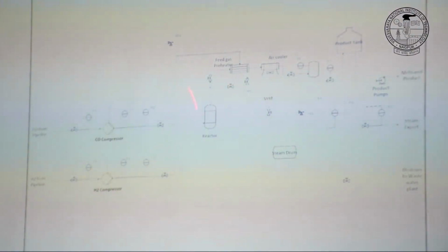After the process control loops on all the systems we see, we can also have a pressure safety valve. Here you could see one common safety valve is downstream of the compressor, because the compressor is something you put a lot of energy into. Think about suddenly somewhere here a valve is closed, and your compressor is running.